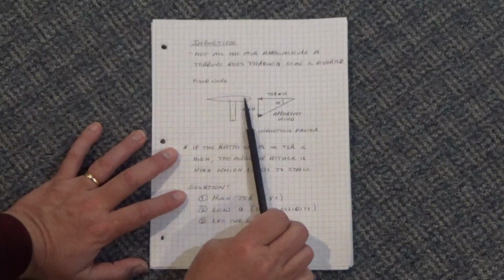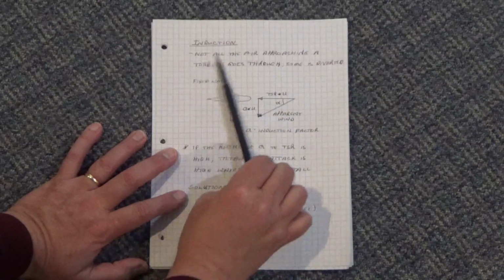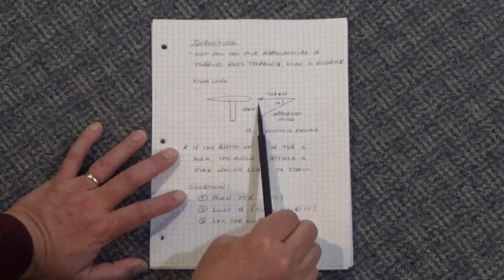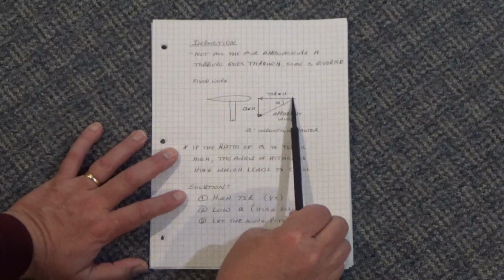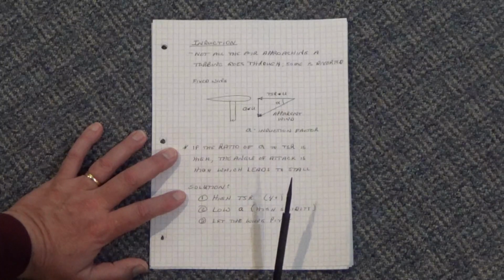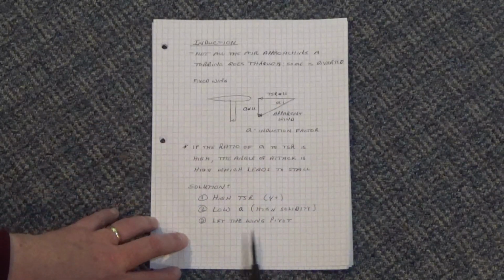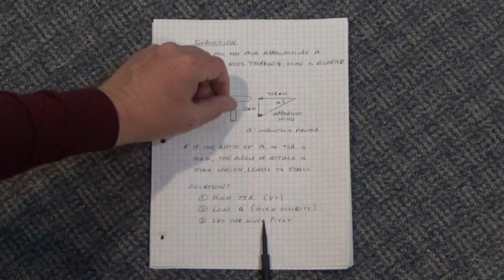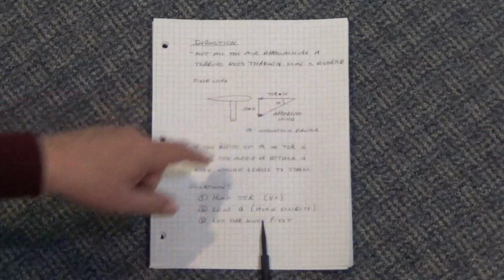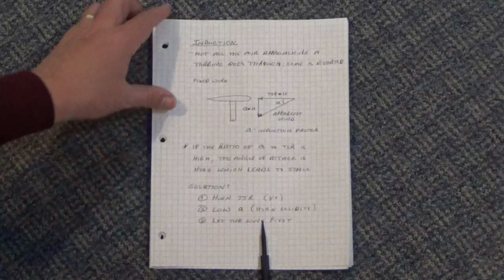So if you have large wings or a lot of wings, then it creates a pressure in front of it, and the wind gets diverted. And so you don't get as much air going through, but it stays attached because this angle of attack is small. And then there's the other solution. You could let the wing pivot, and that's what the Sharp VAWT does. So it allows it to pivot and develop a smaller angle of attack so it doesn't stall.